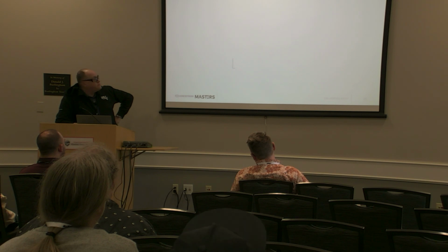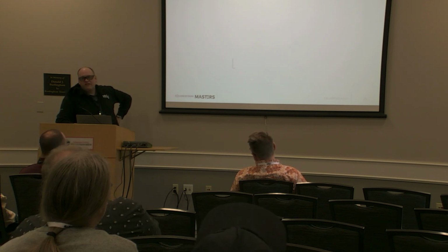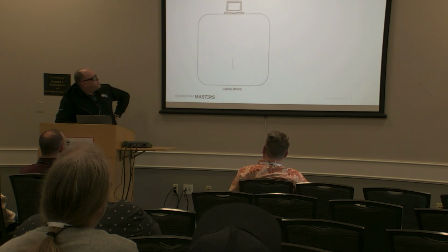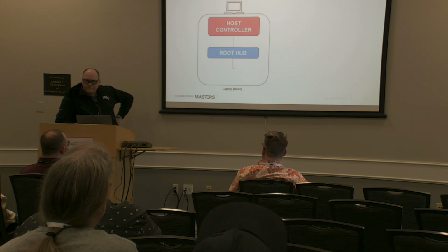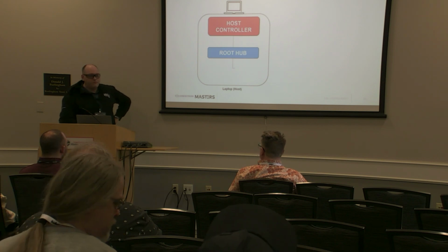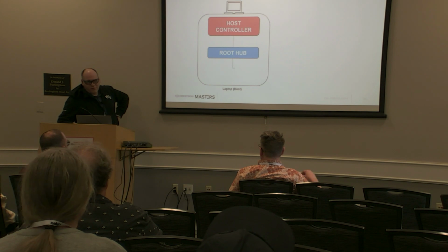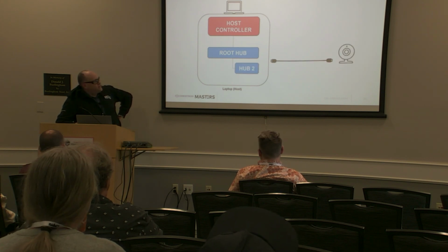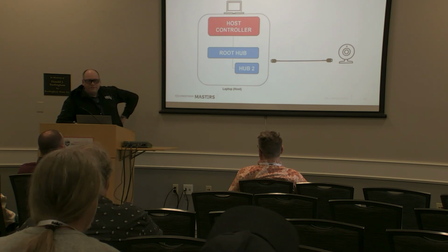Nobody got a guess? There might be multiple tiers in a single hub. That's right. There might be multiple tiers in a single device, right? So your laptop has a host controller. Anybody seen a laptop with more than 4 ports on it? Most of you, if you're designers, you've probably been given a pretty beefy laptop at some point, and it's probably had more than 3 ports on it, right? That's because there is a stacked hub inside of your laptop, right?